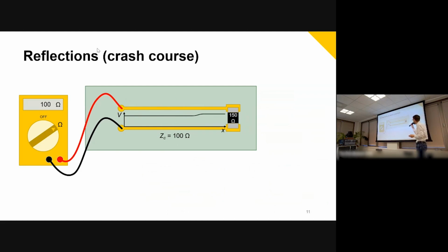And then, hey, there's some kind of surprise traveling back. Because it turned out that the charge front that was propagating, the current, induces a different voltage across 150 ohms, a higher voltage than across this 100 ohms. The surprise travels back to the ohm meter and now displays the correct value. This kind of surprises are called reflections.